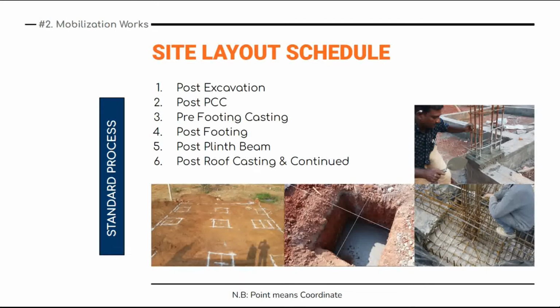Here you need to mark the footing portion. These rectangles you can see here in this image are the marked footing layouts. So this is done post excavation. Then second is the post PCC. After excavation and sand filling, the PCC of 4 to 5 inch thickness is done.